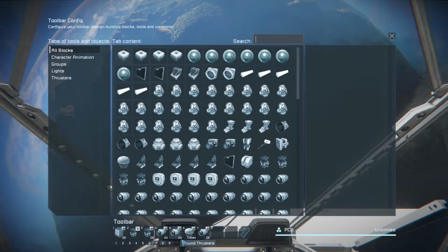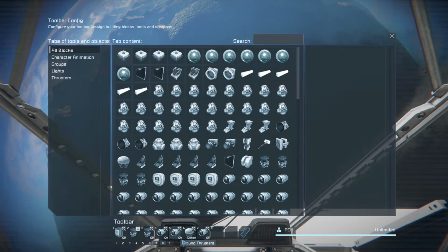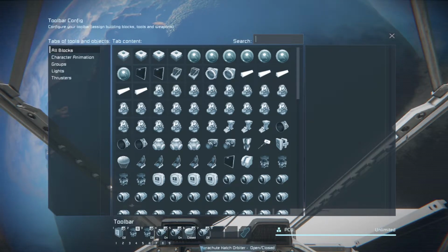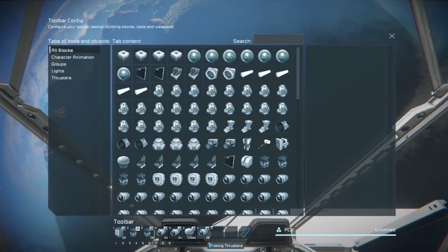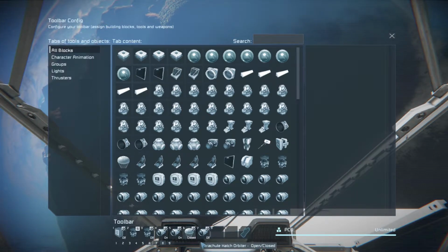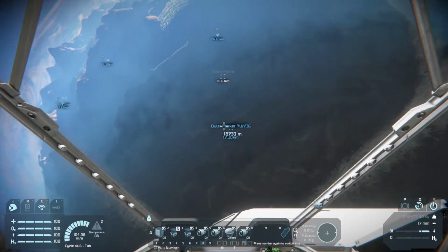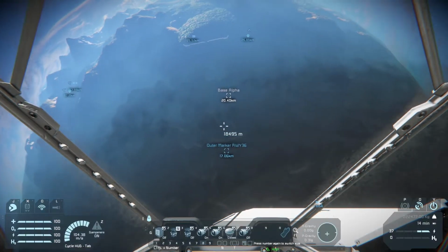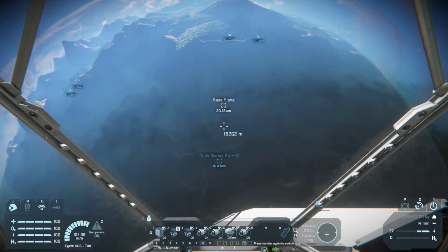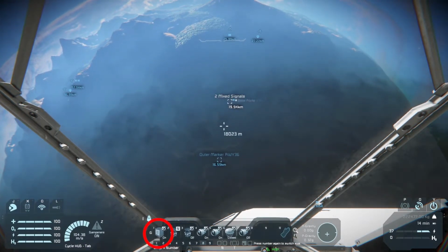These are even more downward pointing thrusters to have some good weight on the wheels. You can open the parachute hatch. That will break it down or slow it down. And then the braking thrusters are to maintain your position, because these are the only thrusters looking forward. If you don't put them on, you just continue rolling, because the parachute cannot brake you down to stop. So this sequence is very important, and just need to know that. So right now we can also already put on the radio altimeter.